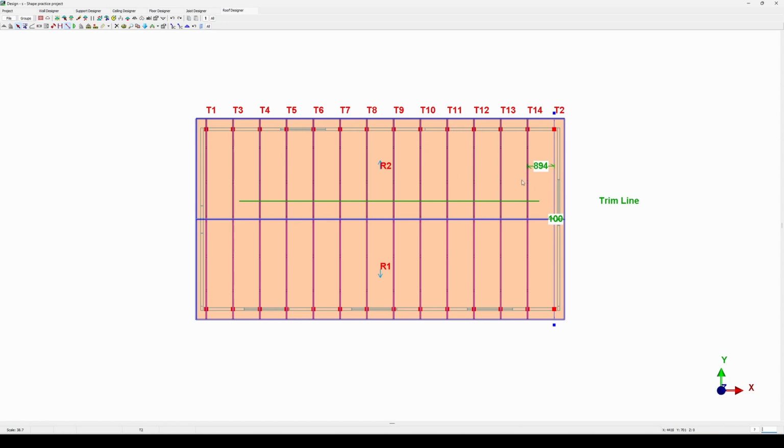Currently, your settings have been created to have a 900mm center to center spacing, and with this tool, it automatically detects the closest spacing to 900 and creates those trusses within those two selected points. If you want to go the route of having exactly 900mm spacing trusses, or whatever preference you've set in your project settings, we're going to delete all but one of the trusses on our project by using the Select Multiple Trusses tool from inside right there to the outside right there.